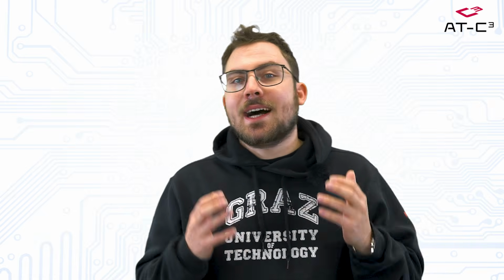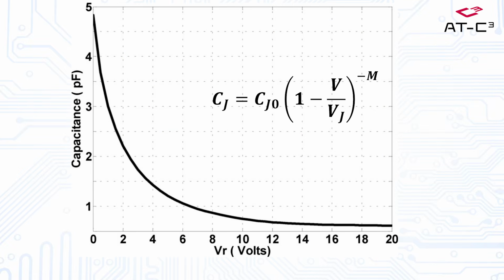Why does a diode cause harmonic distortion when the signal only passes by? The answer here is the nonlinear voltage-dependent capacitance of the diode. Over one period of our RF signal, the capacitance is changing. Thus, we have an interaction between the signal and a nonlinear device.